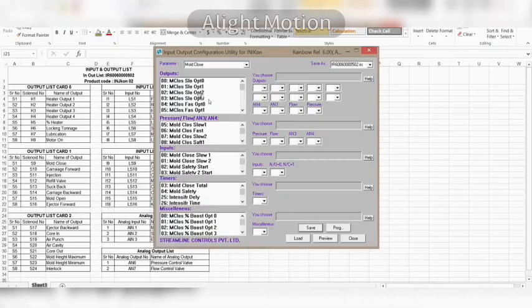You will see the parameters at the top. At the top of the software, you will see in the parameters mold close, core, mold open, ejector, carriage, injection, refill, temperature, and many more parameters. If you want to define a function, you can define it by going into this parameter. Below that, you will see different boxes for each parameter, such as outputs, pressure, flow, AN3, AN4, inputs, timers, miscellaneous.